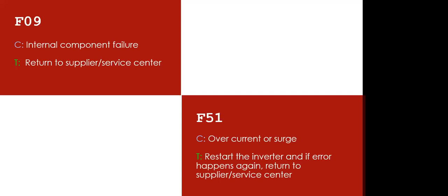What we need to look out for in setting the power limiter is the maximum voltage it should accept from the input, then the maximum charging current it should accept from the input, then the minimum voltage, the low voltage it should accept from the input. All this we need to set on the power limiter in order to protect our inverter.